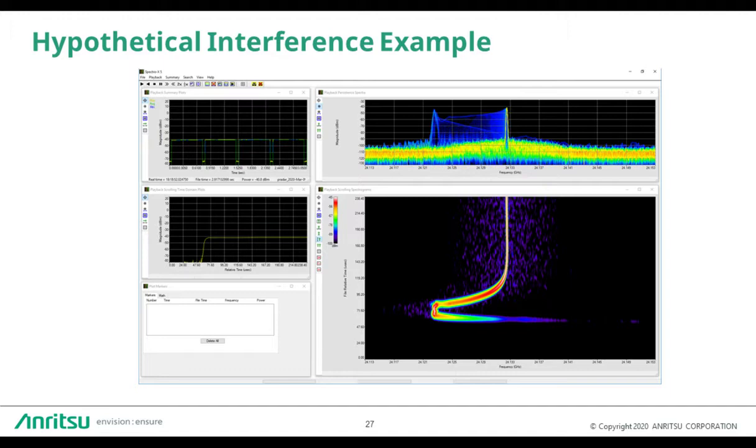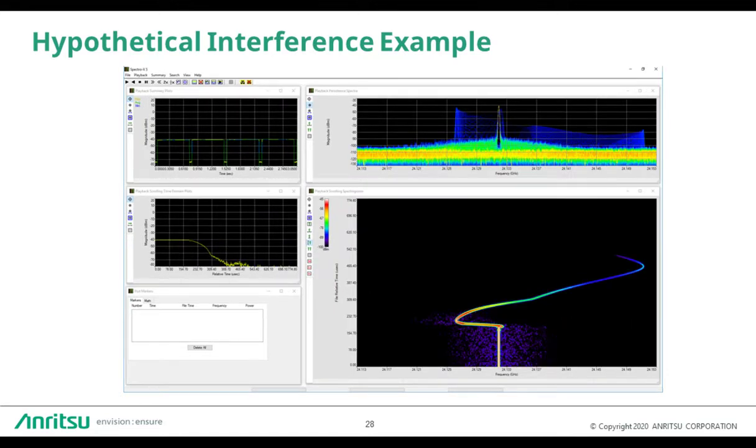In this case, this is actually just a little pocket radar device that anybody can buy off of Amazon. It can be used to test the speed of a golf swing or a baseball pitch, or oncoming vehicles. So it may be that in the vicinity of your transmissions, Saturday mornings, you've got a baseball field, and you have coaches bringing out these devices and they're testing speeds and things. And during that time, you're starting to see drops in communications because maybe this device isn't transmitting exactly the way it should.